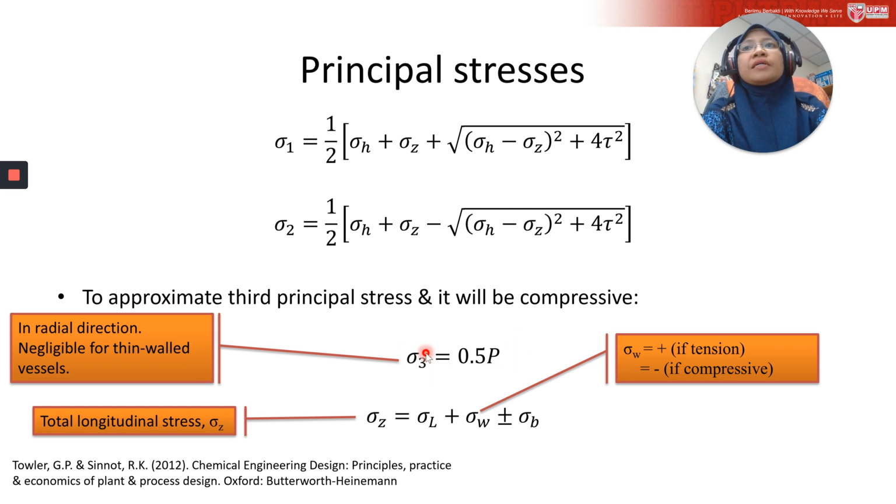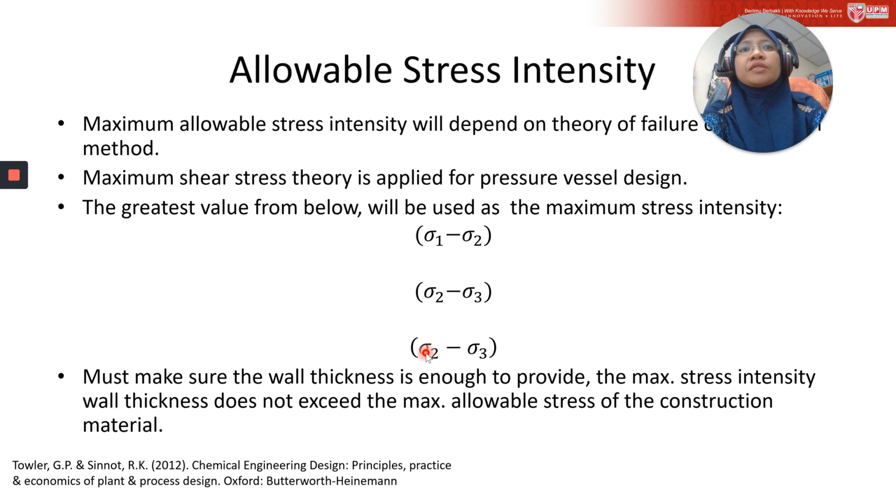Then let's look at the allowable stress intensity. The expression of this will depend on the theory of failure that you adopt in your design method. The maximum shear theory is normally used for pressure vessel design.